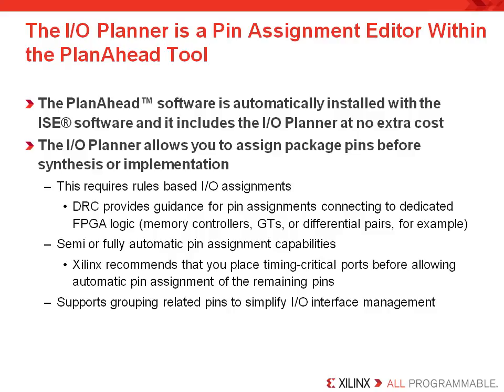Now, the I/O Planner also includes a design rule checker that provides guidance for making pin assignments connected to reserved hardware, such as your serial gigabit transceivers or differential I/O pins. The I/O Planner also includes a unique fully automatic pin assignment functionality. Despite this feature being included, Xilinx recommends you place your timing critical pins first before allowing the remaining pins to be automatically assigned. The I/O Planner also supports grouping I/O pins when assigning them. This simplifies the management of your I/O interfaces.